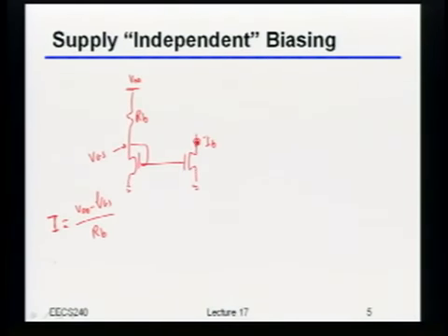What this one is going to try and do is, there's kind of another way, right? Which is, okay, let's say that somehow I can tweak this VGS by sizing the transistor or something like that. And instead, what if I just made this RB really big, right? If I make that RB really big, then this will be the large signal bias current, right? But now I can look at, from a, let's say, quote-unquote, small signal standpoint, how much change in current you would actually get, right?